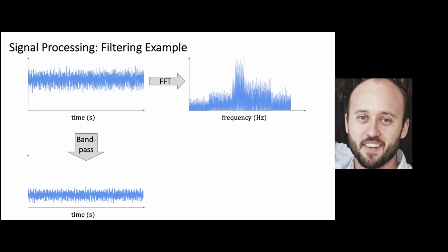And then if we looked at that bandpass filtered vibration signal in the frequency domain, what we would see is that band of frequencies is targeted. And maybe in this instance, because we have some domain knowledge of the system, we know that this is a specific frequency range that we want to target, so it can help us study it.